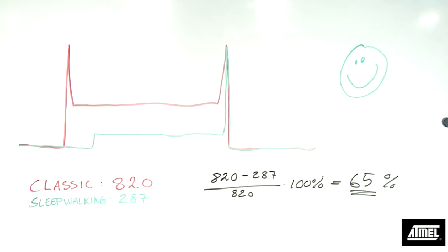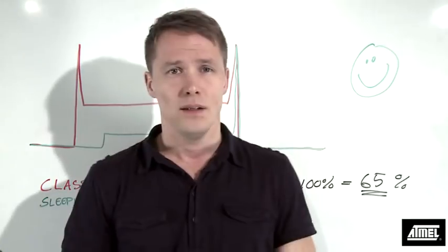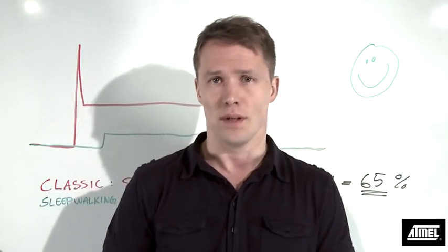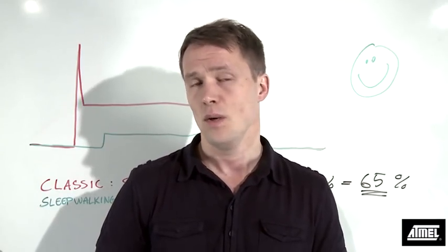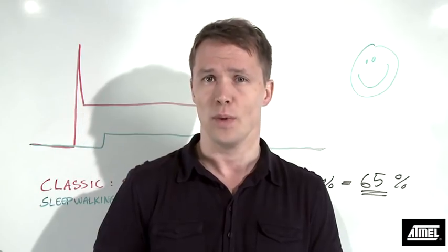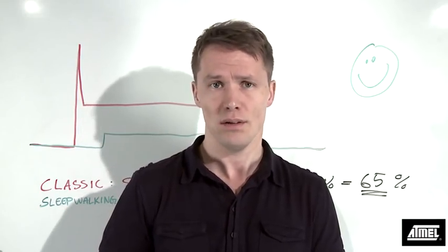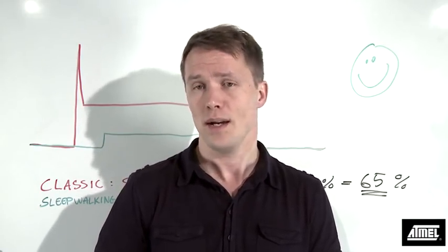We could be monitoring temperature, supply voltage, or an analog control dial. We could be monitoring a capacitive touch panel for touches. A 5 millisecond response time is much less than noticeable. You can also use sleepwalking with other tasks, like evaluating addresses on a multi-slave communication bus, where traditionally all slaves would wake up and have the CPU inspect all data to determine whether it should be acted upon.